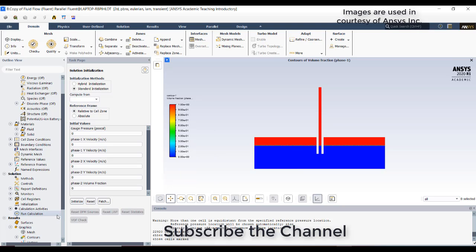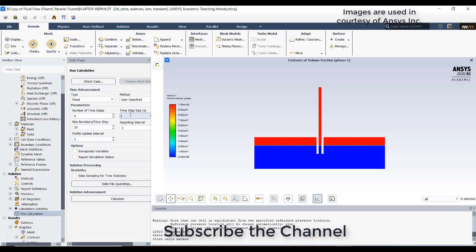Go to run calculations. I have created 1e power minus 4 as my time step with 1000 as the number of time steps. Click on calculate.